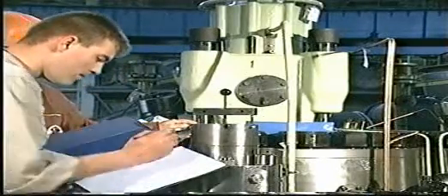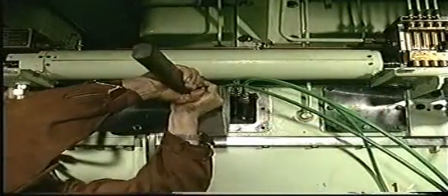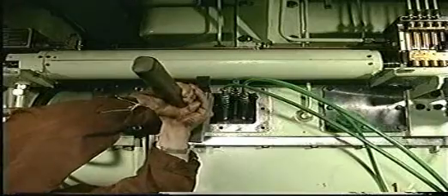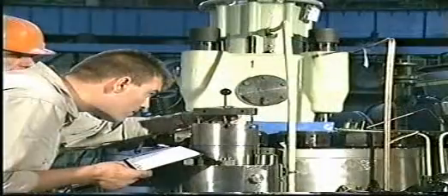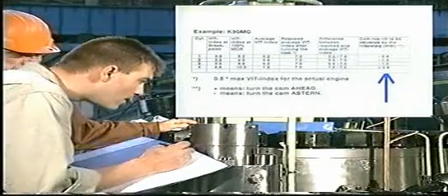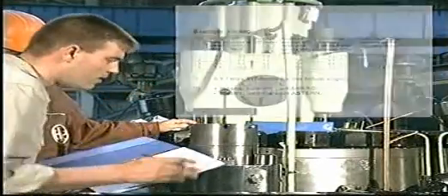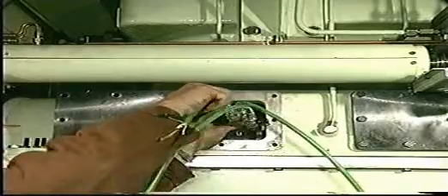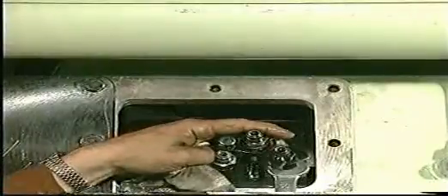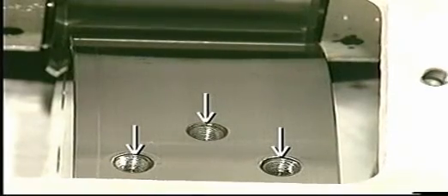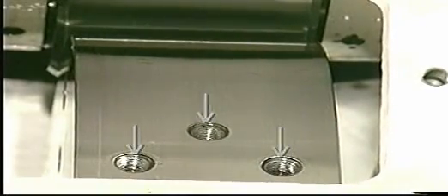Read the measuring tool once again before turning the cam. Turn the cam in the required direction. See also step 1.4 of this film. Follow the turning of the cam on the measuring tool and stop turning when the required change has been obtained. Relieve the system of pressure and remove the spanner and hydraulic tools. Leave the cams to settle for a minimum of 15 minutes and then mount the plugs.